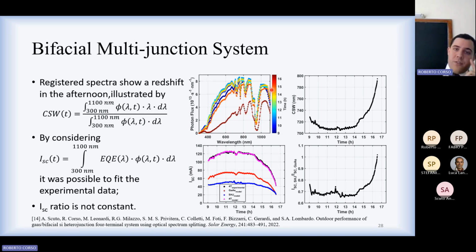Whereas we saw that in the end, the parallel coupling through the voltage match is much more stable. And that is because the open circuit voltage of a solar cell depends logarithmically on the incident irradiance, whereas the current depends linearly.